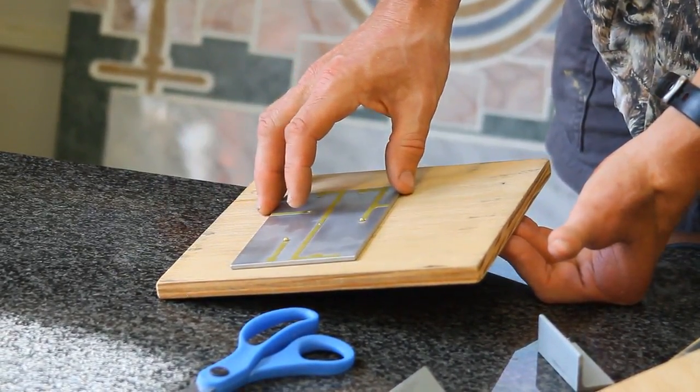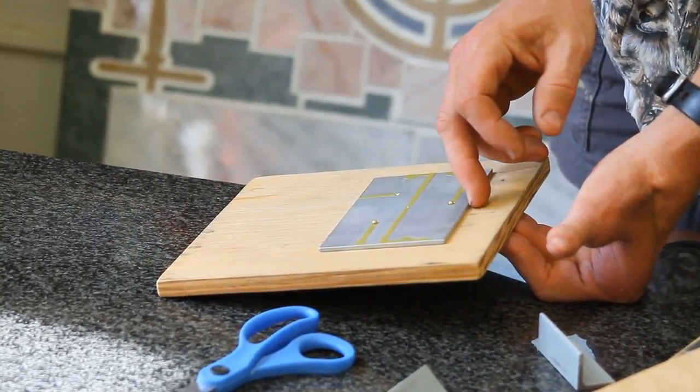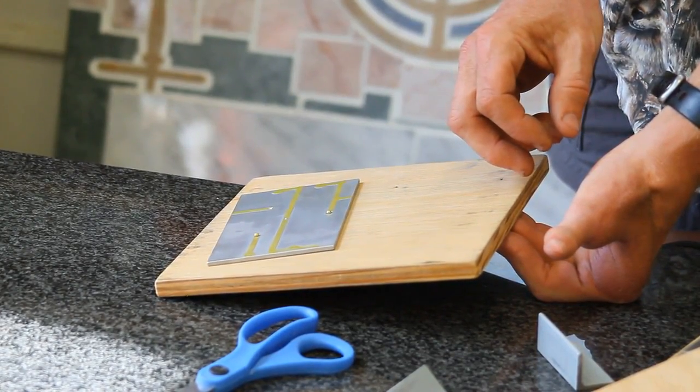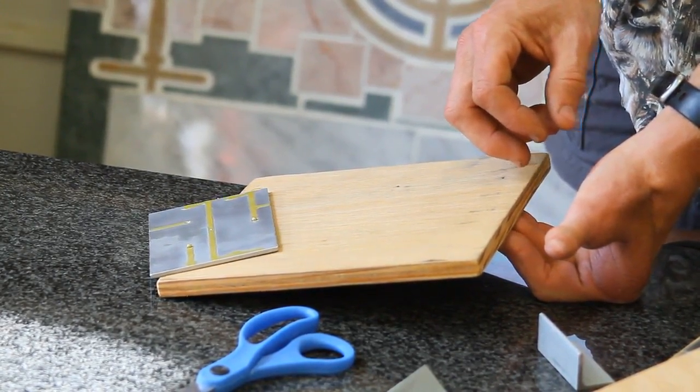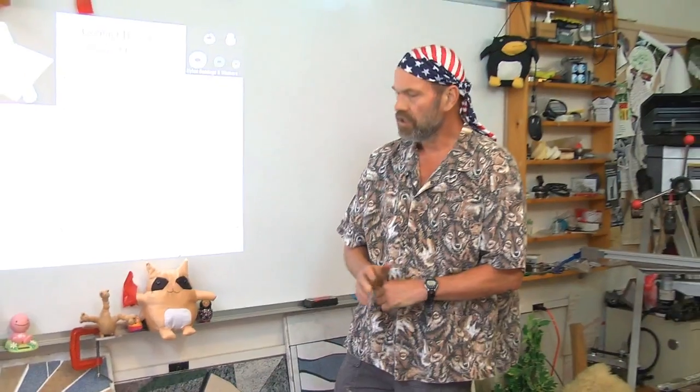I can go to a slightly lower angle and get it moving, and it'll keep moving. See how I haven't changed it. That's the difference between dynamic and static coefficients of friction. Different materials will have different friction coefficients between themselves and other bodies.